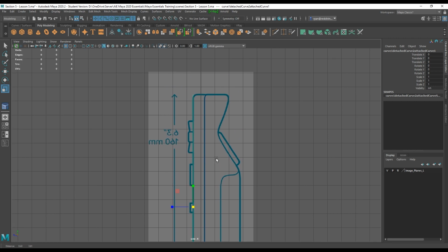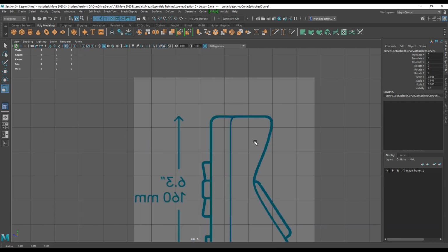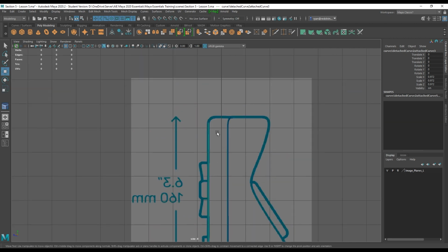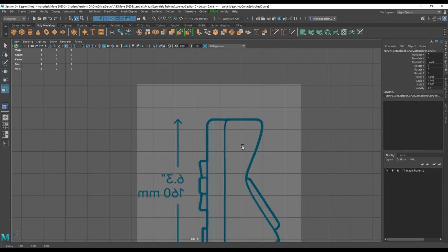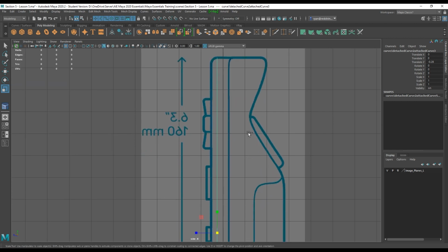I'm going to scale this bad boy down so that I can get to its innermost point. Then I'm going to Control D, W, move it. I'm going to move it out backwards. I'm going to take it about, say, here to its most extreme point, like so. And then Control D, then Control D again to move it somewhere in between and then scale it down. As you can see, we should get a nice rounded surface, but we can tweak it after the fact.